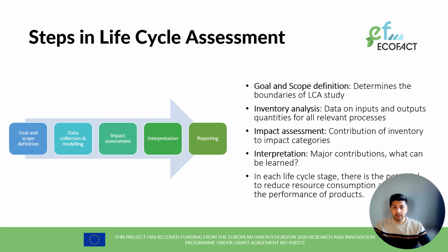Now, understanding life cycle assessment involves a few key steps. First, goal and scope definition that includes setting up the purpose and the boundaries of the environmental study. Life cycle inventory analysis that includes gathering data on resources used and the emissions at every product stage, creating a comprehensive inventory. Lifecycle impact assessment that computes the contribution of this inventory towards the chosen environmental impact categories, which we will come to in the next slide. And finally, the interpretation that provides meaningful insights.